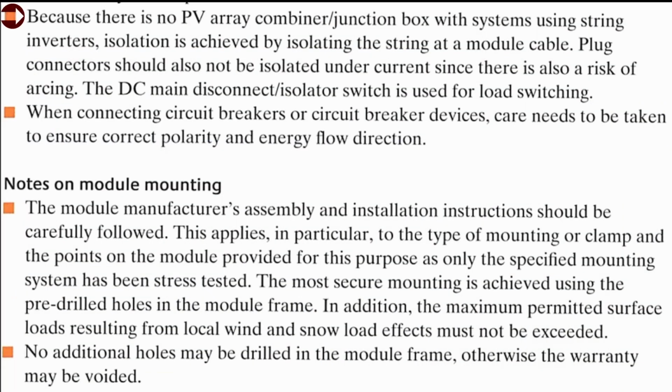You don't need this combiner box or junction box with systems using string inverters. So this makes it cheaper and less fault-prone, with a lot fewer faults, also more shadow tolerant. And when connecting circuit breakers or circuit breaker devices, care needs to be taken to ensure the correct polarity, the energy flow direction. As I mentioned already, nowadays the plugs are fail-safe, but not the circuit breakers and the other installation. You have to really check this before.